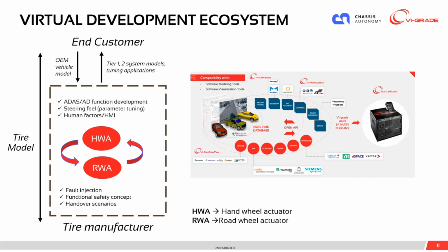So you can work on ADAS and AD function development. Is my function interfering too much? Is it interfering too little? Is it too aggressive? You can, of course, do a lot of steering feel parameter tuning. You can do the tuning, variable ratio tuning, depending on the speed. And of course, how can you forget HMI, which is extremely crucial nowadays. You can also work on fault injection.